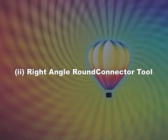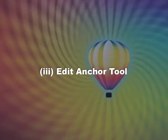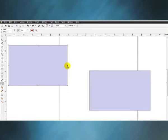Second, right angle round connector tool. The next option of this tool is the right angle round connector tool. This tool draws a right angle connector with rounded corners between the 2 objects. Third, edit anchor tool. The next option of this tool is the edit anchor tool. This tool edits anchor points of connecting lines between the 2 objects. So viewers, the 6 options of the toolbox remain and could not be completed in today's episode.